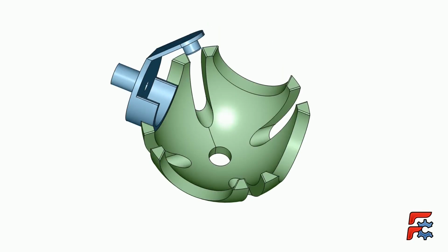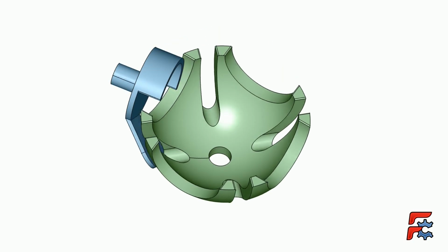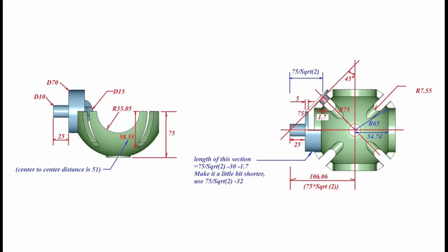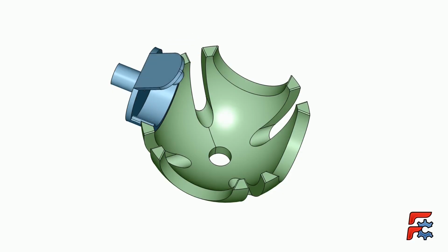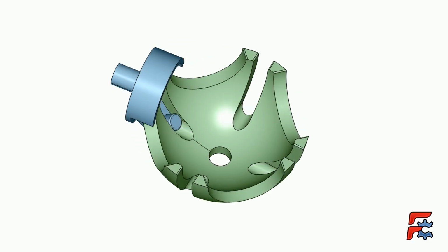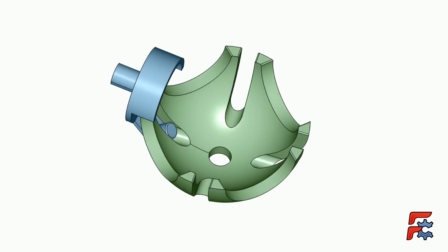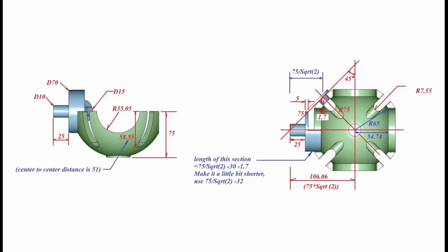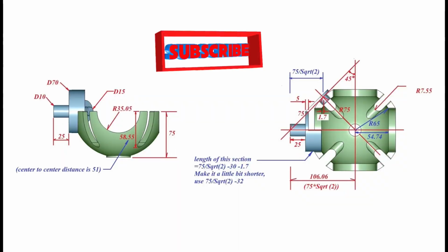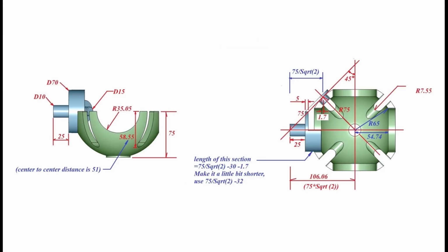Anyway, it is a good example for Assembly 4 workbench with intermittent motion that cannot be achieved by the default assembly workbench in FreeCAD 1.0. These are the major dimensions of the Spherical Geneva mechanism. The idea is using a 75 mm arm at 45 degrees with a pin to drive a sphere with radius of 75 mm. The pin moves along the slots at the sphere to turn the sphere. The semicircular structure at the arm is used to stabilize the sphere when the sphere is not turning. Once I decide the radius of this structure, I can start to construct it and only simple calculation is needed. Then I will set up the relationship between the motions of the arm and the sphere, so I can apply it in Assembly 4 for the simulation.